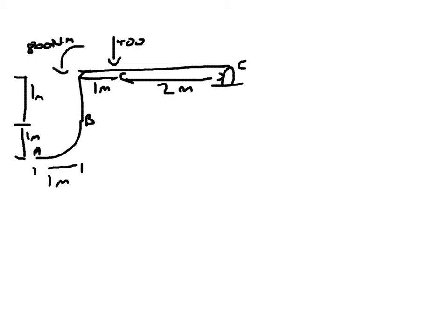You've got a force at either end, so we can recall that the resultant force will be acting along the line that connects A and B. We know that that's 1 metre down there and it's 1 metre across here, so we've got an angle of 45 degrees in each section there. So that'll be useful for later, so we can now simplify this onto a free body diagram.